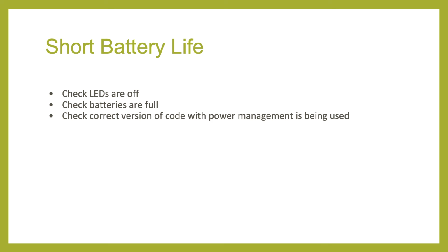So now let's go through some common issues on the WildLogger that might come out of our lab, sandbox and piloting. If you're getting a shorter battery life than expected, check the LEDs are off, the batteries are full, and the code you're using has power management.